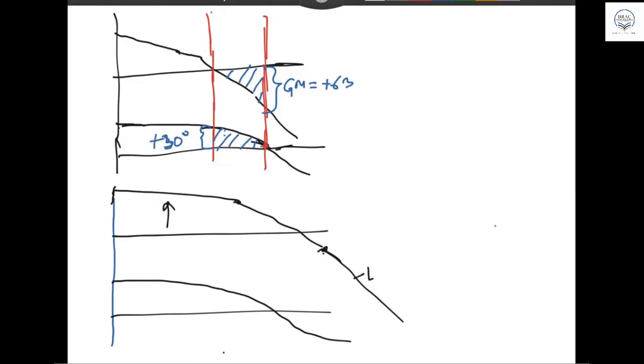It is LM, and this is PA. So the PA curve is the same. The PA curve I'm just giving is the same, but the log magnitude curve is changing, so the curve has gone up. Let's say this is the scenario, in that case, what happened? This is the log magnitude and phase angle crossover frequency point, omega g and omega p are changing. Last time this was omega p, and this was omega g, and this time it is omega g, and this is omega p, right? According to the definition, that is what happened.